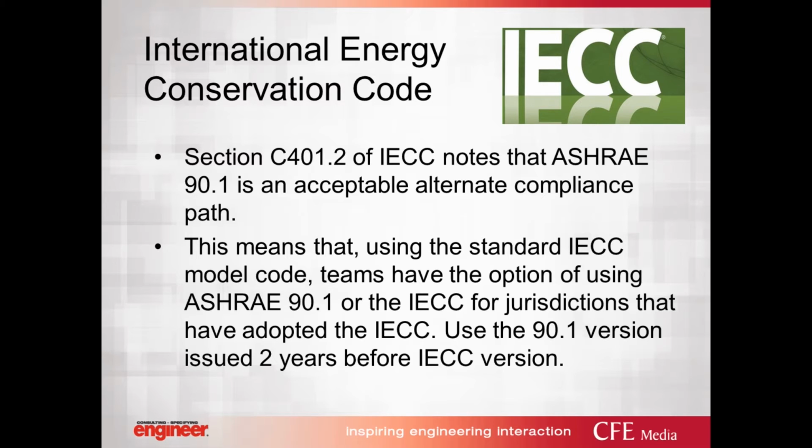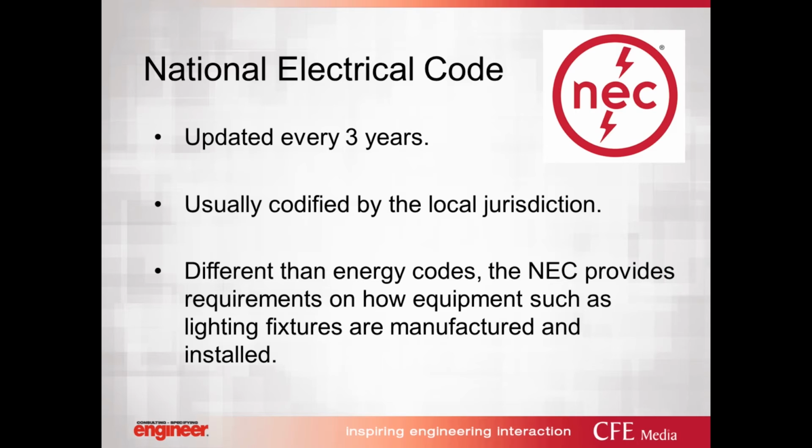The IECC does have a section that allows you to use ASHRAE 90.1 as an acceptable alternative compliance path. That means teams have the option of using either one. If you are using the 90.1 version, you want to use the one that's 2 years before the IECC version. For example, in Ohio, the IECC version is 2012, and that would be ASHRAE 90.1, 2010. Again, just a reminder to check with your design team to make sure that everybody is using the same energy code.